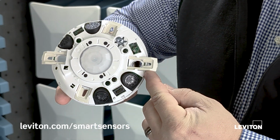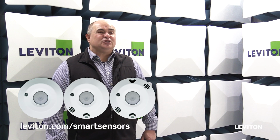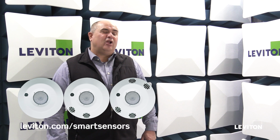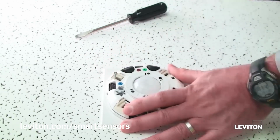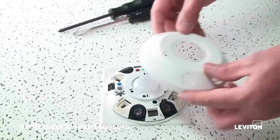You then can take your screws, and instead of trying to balance them on a given screwdriver tip, you can put those screws into the box, screw them in a little bit just so they don't fall out, and then push the smart ceiling sensor or smart room controller over those screws. Once it's in place, you merely move those wings back in, now holding the sensor captive on those screws, and then you finish tightening them down.